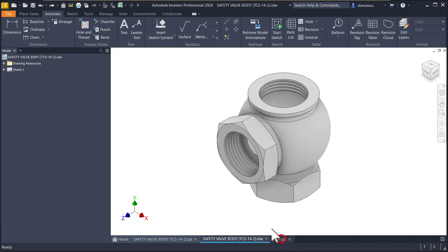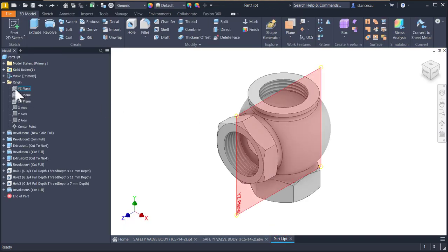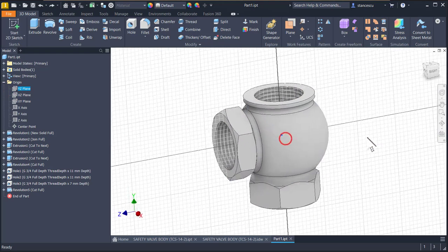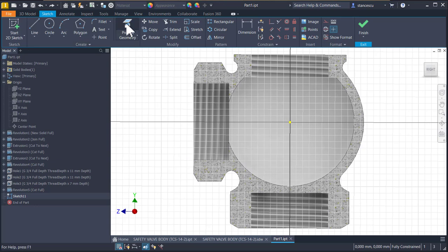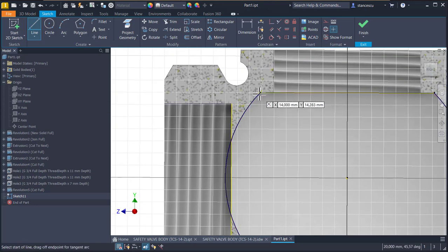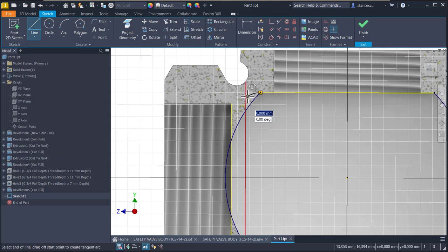Let's create this sketch. This is the plane F7. We project this line and this line. We draw a line which is an arc. Press the left button, go to the left, and now to have a smooth movement, I press the Control key.